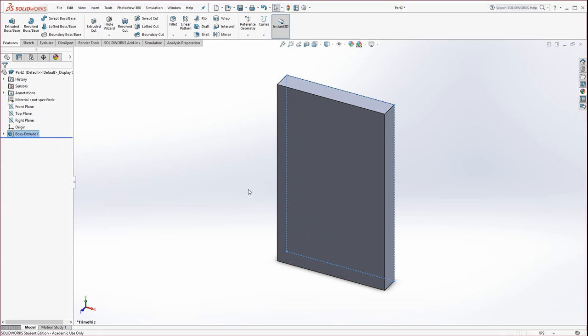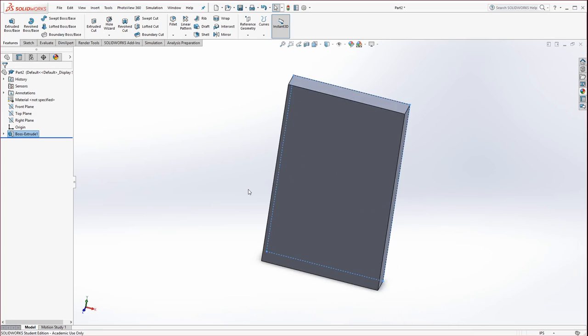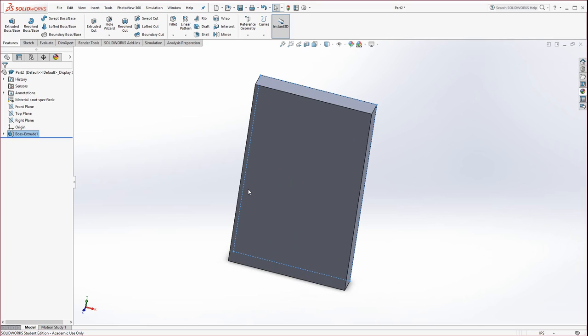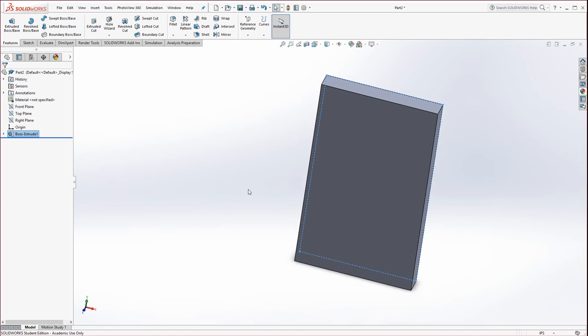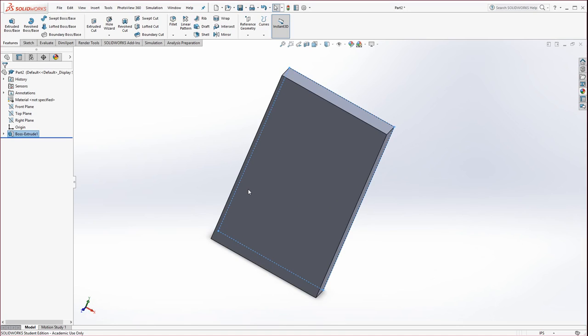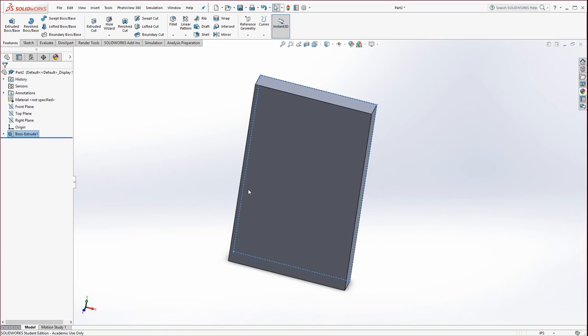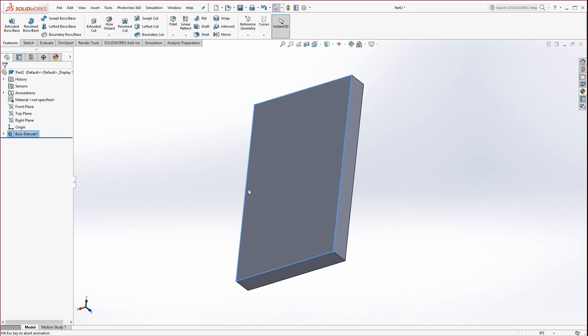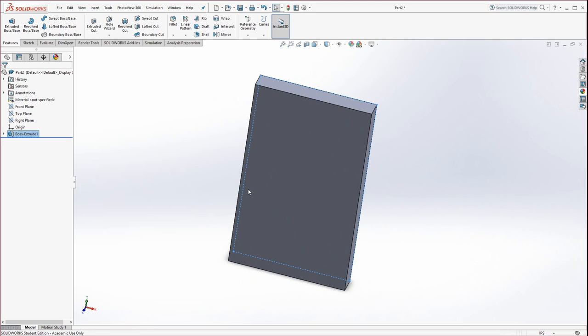Now, to rotate a solid, I'll show you the fast key first. Look at the keys on your keyboard, the little arrow keys, up, down, left, and right. Go ahead and hit them. It rotates in 15-degree increments. Now if you hold Control and the arrow keys, that pans left, right, up, and down. That's Control with the arrow keys. If you hold Alt with the arrow keys, it rotates clockwise and counterclockwise. Only the left and right arrow keys function for that. And if you hold Shift and the arrow keys, it rotates in 90-degree increments. So there's just a few extra fast keys for you to learn.